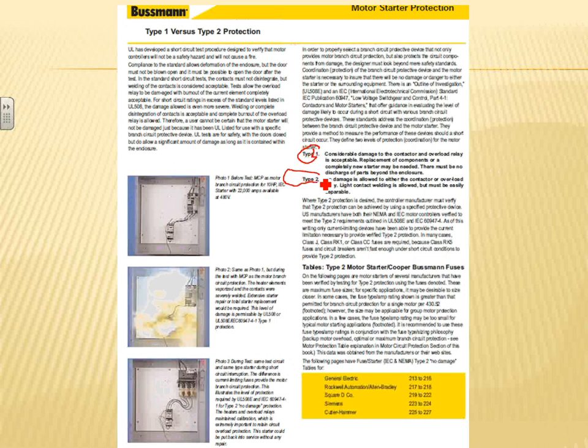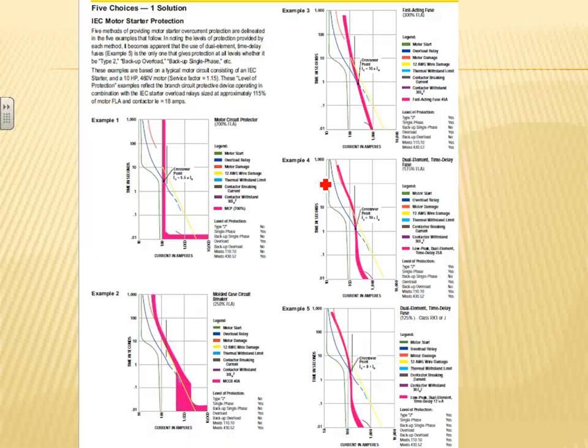They talk about type 1 and type 2 protection. Type 1, basically minimum damage to the equipment. That's exactly what the NEC code requires. Minimum damage to the equipment if you have a short circuit condition. You might have to change the circuit breaker or adjust certain things, but nothing will burn. Type 2, no damage whatsoever to your equipment. If you have an overcurrent protection device, if you use a circuit breaker, and you have type 2 protection, meaning you just literally change a fuse, or for a circuit breaker, flip it, and off it goes. So when you get into type 2 protection, especially at a higher short circuit, you almost have to go to a fuse.